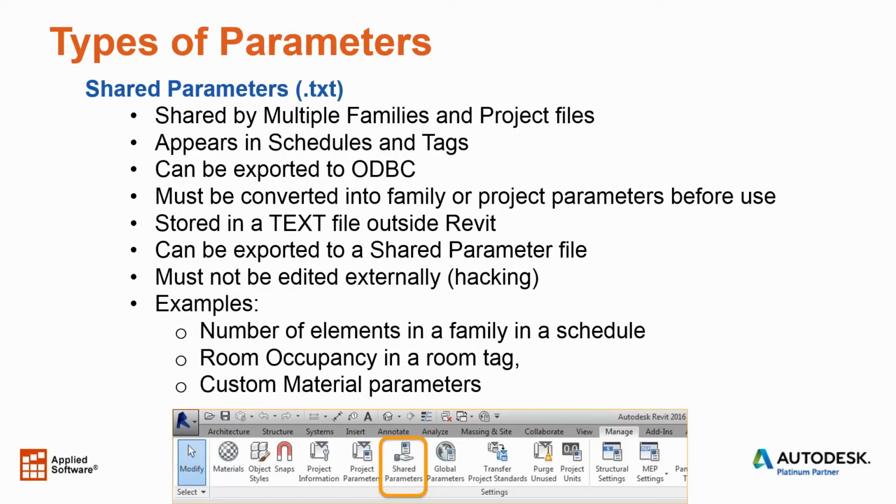So shared parameters must be converted into family or project parameters before use, and they are stored in a text file outside of Revit and can be exported to a shared parameter file after use, but they must not be edited externally. So hackers out there, be careful when you edit the file externally. That is not recommended. Unless you know what you're doing, you should not do that.